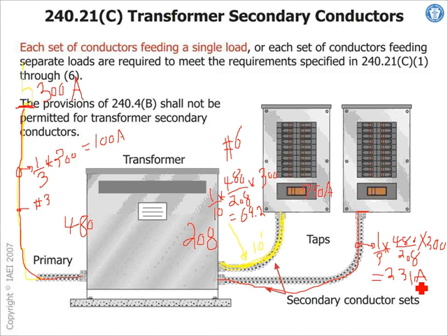Now we start to make something substantial. Cannot be smaller than 231 amps. What would that be? 250 MCM. So that conductor, under these circumstances, cannot be smaller than 250 kcmil. Thank you. You're going to get extra credit for next year for answering.